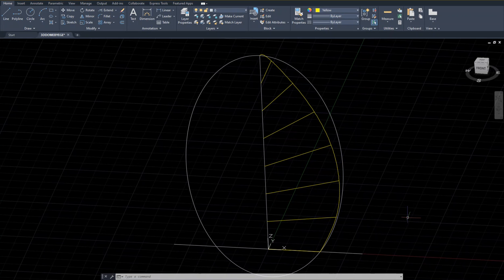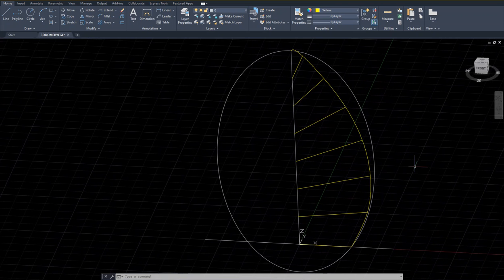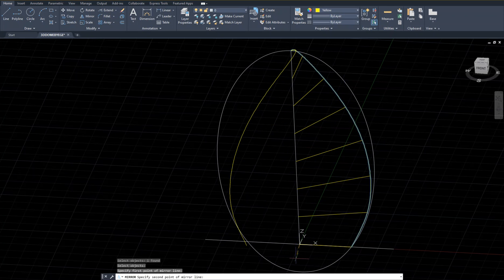Also, we're going to need a different line, a symmetrical line. I wonder if we can do symmetry. Symmetry is a symmetrical axis. The mirror command perhaps will help us. So you click on that, select the spline that you generated, and enter. Now, what is the first point of the mirror? The first point of the mirror would be your 0, 0 point. Click on it.